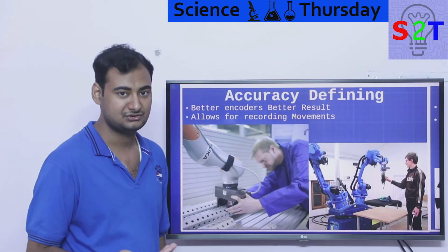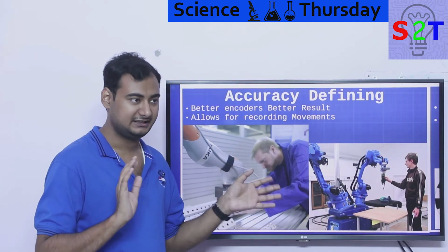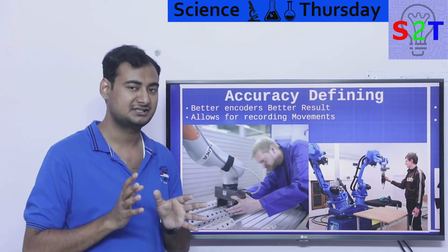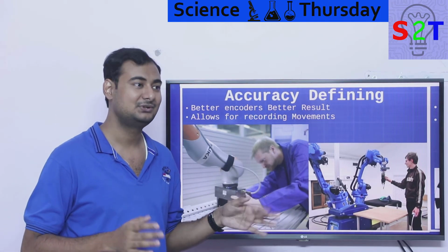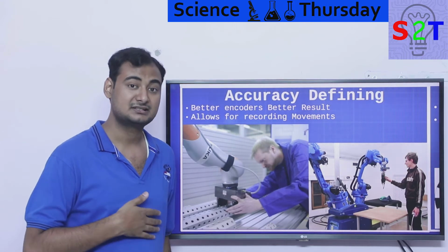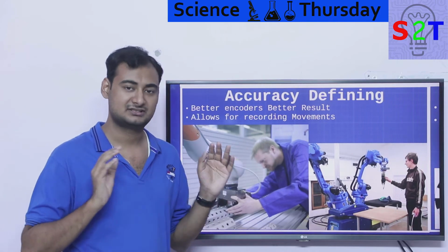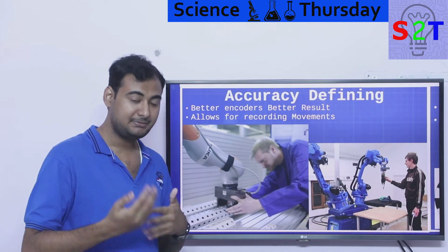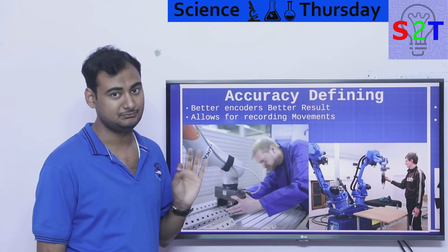Even people who work in machine shops can tell you, if you have a cheap DRO, they are generally capacitive. A side effect of that is if dirt and grime goes directly in between the rail, it will mess up the reading. Not too much, but it will mess it up. But sometimes, let's say you are working at NASA and precision is absolute, then you might use inductive calipers. Those do not care, and there are some systems where you simply cannot mess it up. You can heat it up, it will still count exactly. You can put oil in there, it will still count accurately. So depending on your scenario and your requirements, people use different encoders. So better is better results.